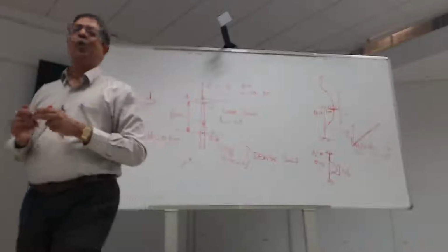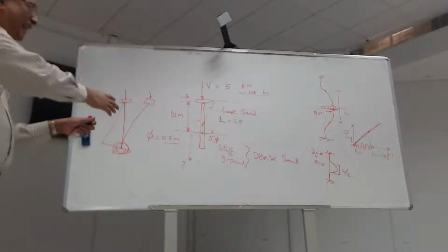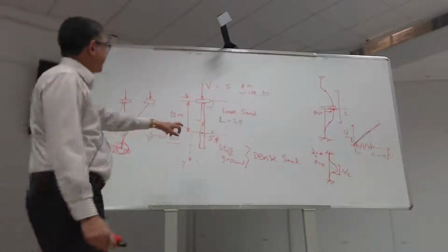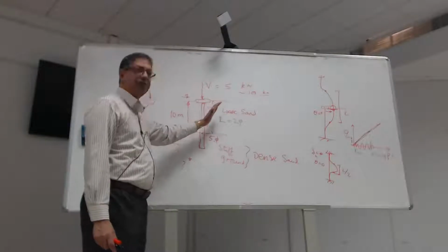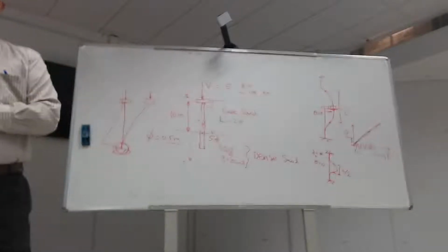And this is why you need to strongly believe in the critical state framework. If the critical state tells you that's what the soil will do, it has to do that. And now you bring that thought back with you. So my p' is now going up, not because the total stress is changing, but because my soil is going into suction. Then this is getting stronger. The soil, as the pile starts to move, will try to get stronger and oppose the movement of the pile.